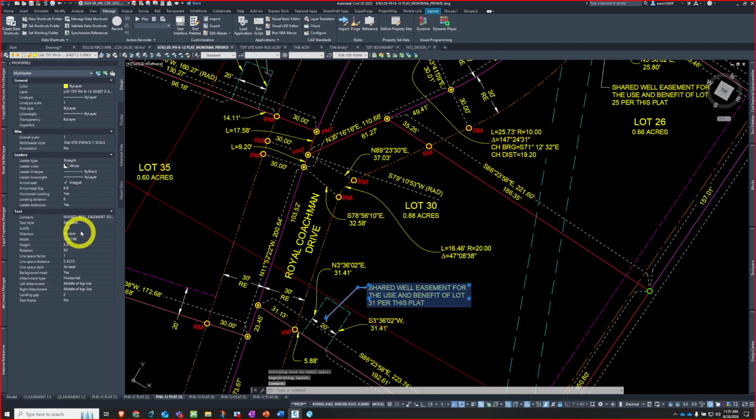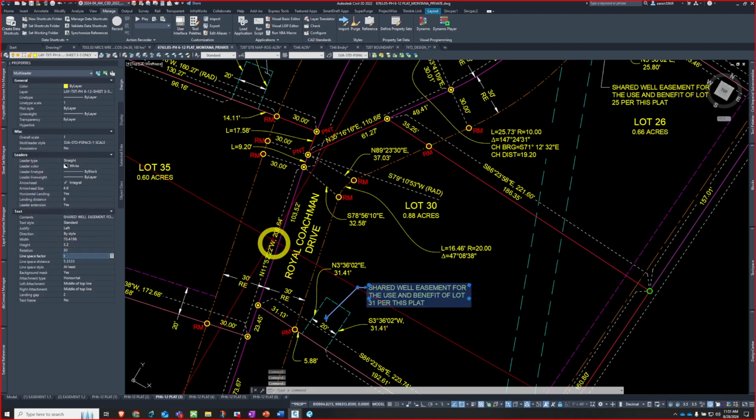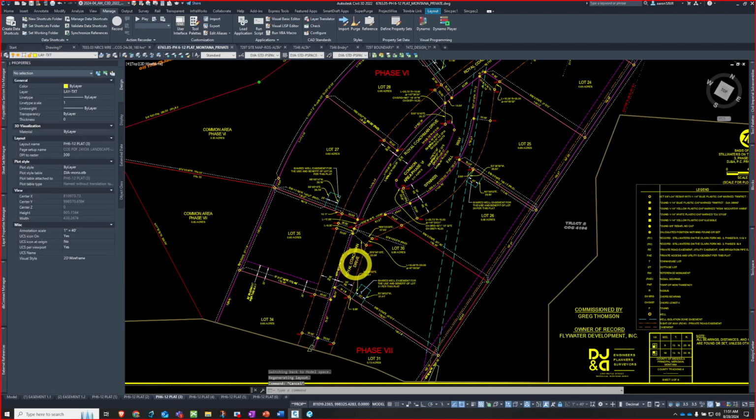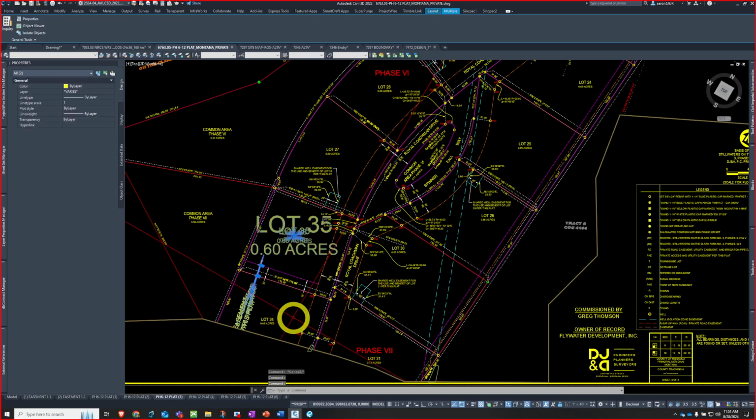So if you do make them annotative, you have to give them a manual rotation to the viewport, which I did here. I made them 30 degrees because when I brought them from paper space, they were awkward like that. That's the one thing you can do. M leaders are a pain in that way, being an annotative object, but M-text and dims are a little easier.